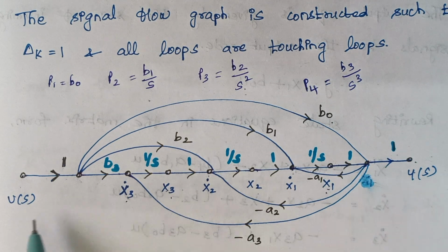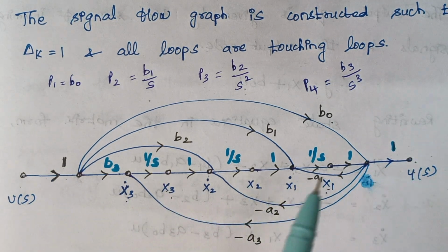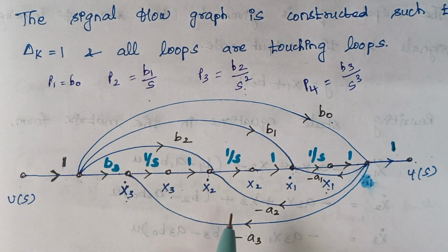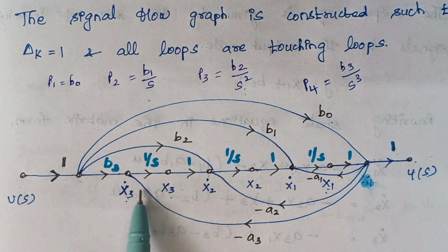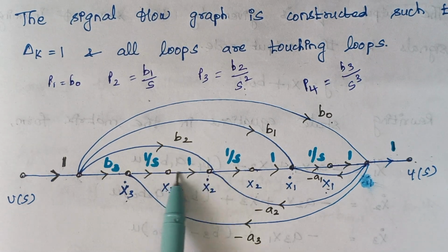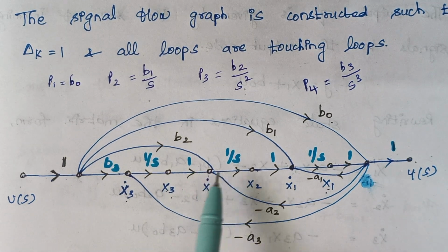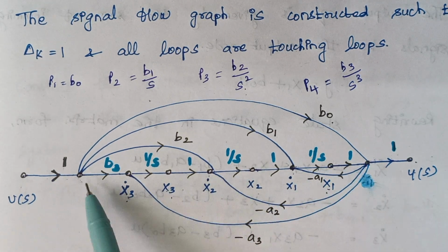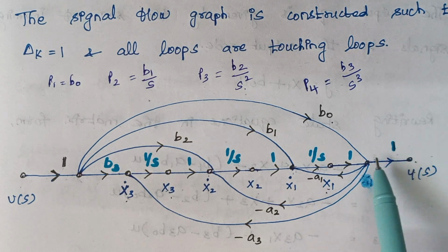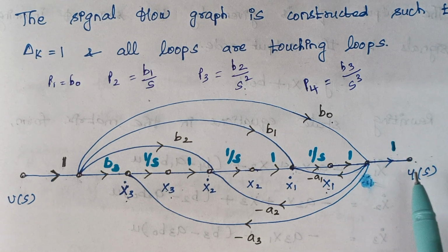The first step is you have to know how many nodes are there in a signal flow graph. That is your first thing. And the next thing is you have to place the state variables in the respective nodes, right? So once you place the state variables, then whenever there is an integration, you have to introduce 1 by s, or else just the gain, and that part of the loop is 1. That's it. When you finish this one, drawing these forward paths is pretty easy, right? So now the forward path gain is calculated.